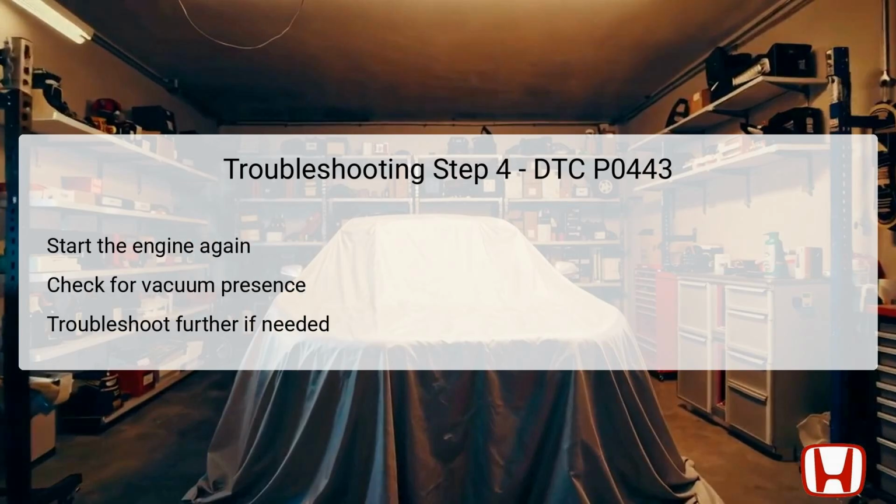Now start the engine and let it idle once more. It is important to observe whether there is any vacuum present at the gauge. If a vacuum is detected, this indicates that the purge valve is likely functioning correctly, allowing vapors to flow as designed. Alternatively, if there is no vacuum, this suggests a potential blockage or issue with the purge valve itself or